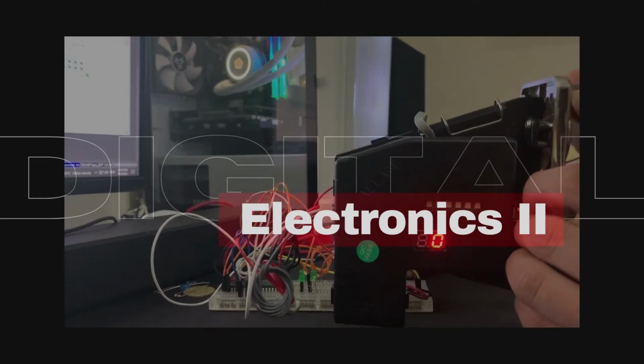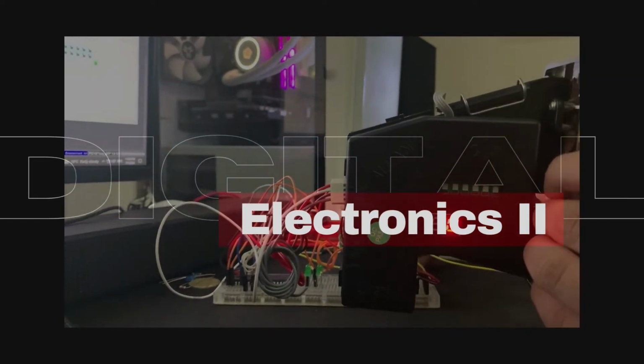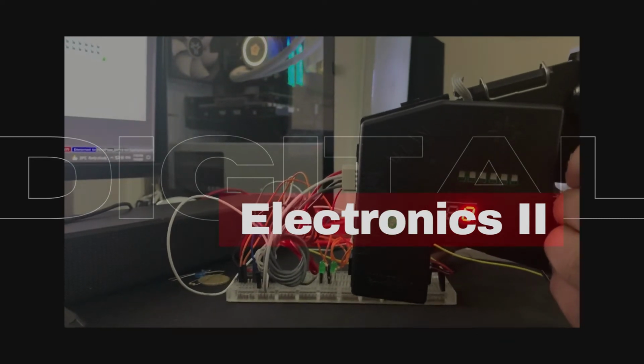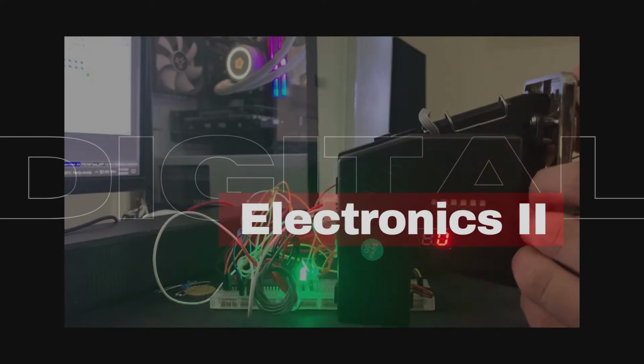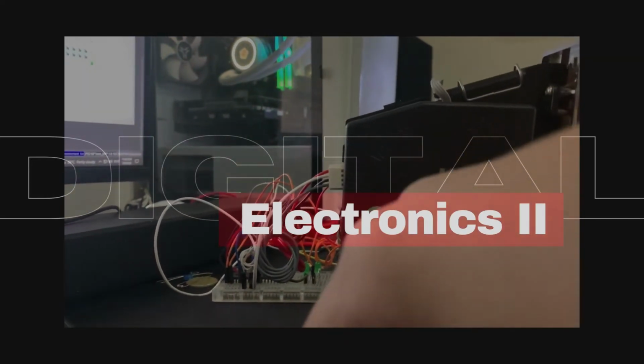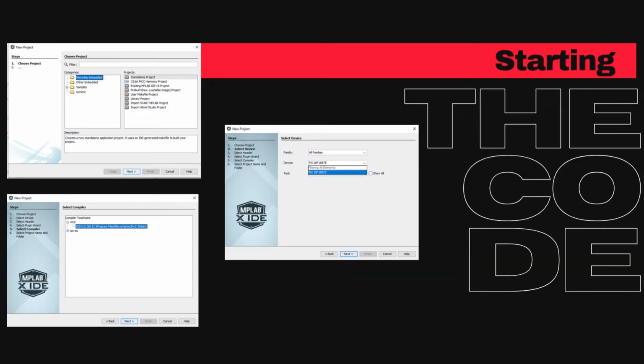The objectives of this project are: when a peso coin is inserted in the coin acceptor, the LED at port B0 will turn on for 2 seconds. And when a 5 peso coin is inserted in the coin acceptor, the LED at port B1 will turn on for 5 seconds. The researchers will be using the MPLab X IDE program for this experiment.